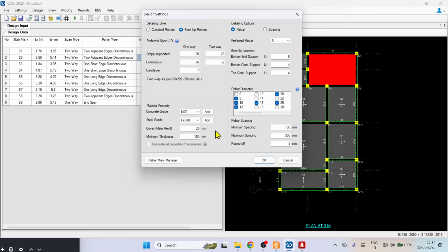Okay, and Fe 500 also has categories, two or three categories. It is given in IS 1786 2008. It is normal, it is ductile, or it is more ductile. Three types of category are there. So we will discuss that later in 1786. There on the board, one code is written, IS 1786 2008, mechanical properties of steel, on the right side, near the door, at the bottom. In that you will find the mechanical properties of steel, and from there the three categories.